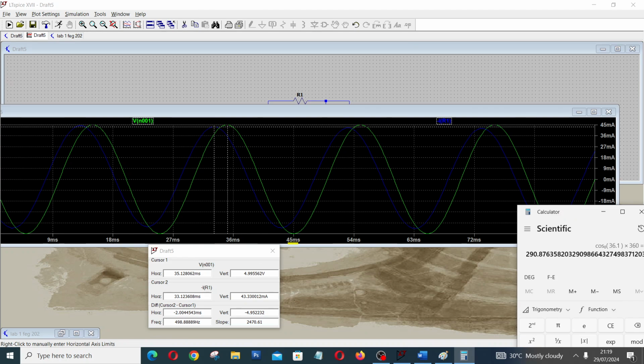Worthy of note is the fact that when you are using capacitors, you can have a series of capacitors connected in parallel, and in the laboratory we call it a capacitor bank. Each capacitor in the bank is connected to a switch, so that you can flip the switch to see the effect of one capacitor before you add another one. If you have gotten the desired value from one capacitor, you stop your correction. But if you are not satisfied, you switch on another capacitor in the bank till you get the desired power factor.